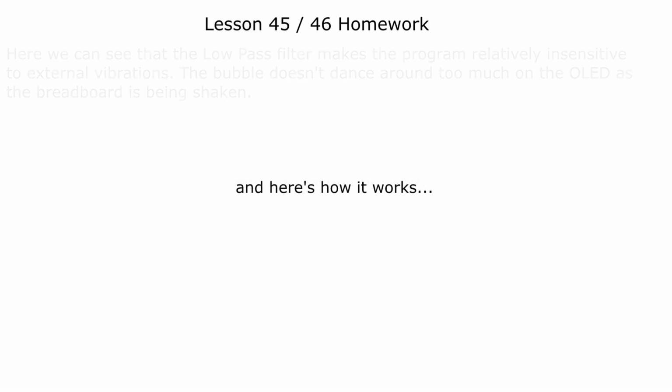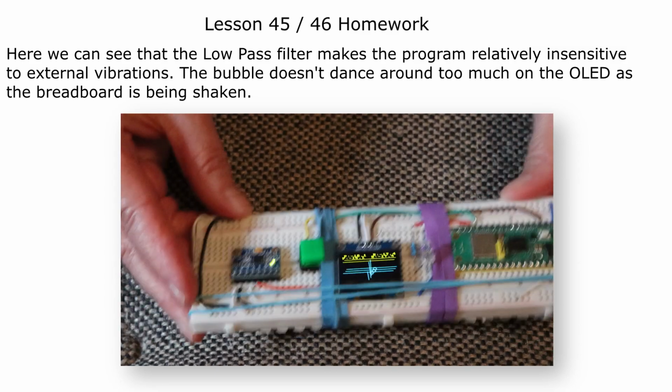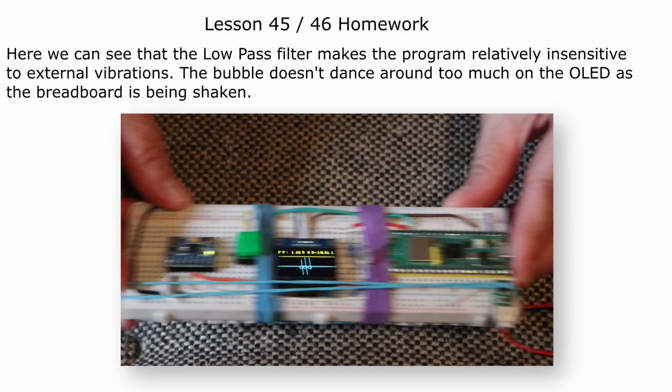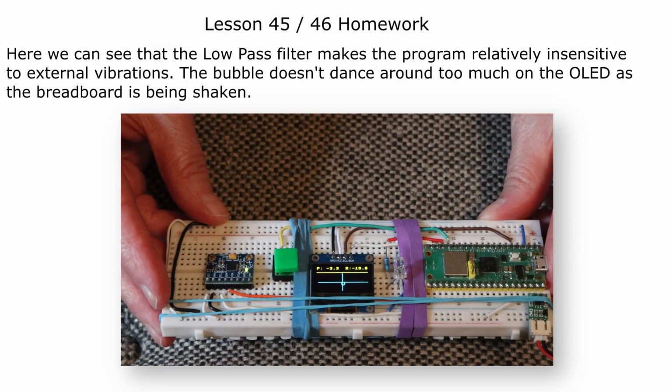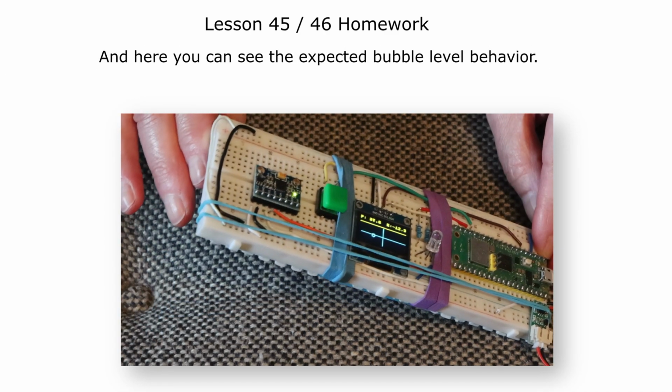And here's how it works. Here we can see that the low-pass filter makes the program relatively insensitive to external vibrations. The bubble doesn't dance around too much on the OLED as the breadboard is being shaken. And here you can see the expected bubble level behavior.